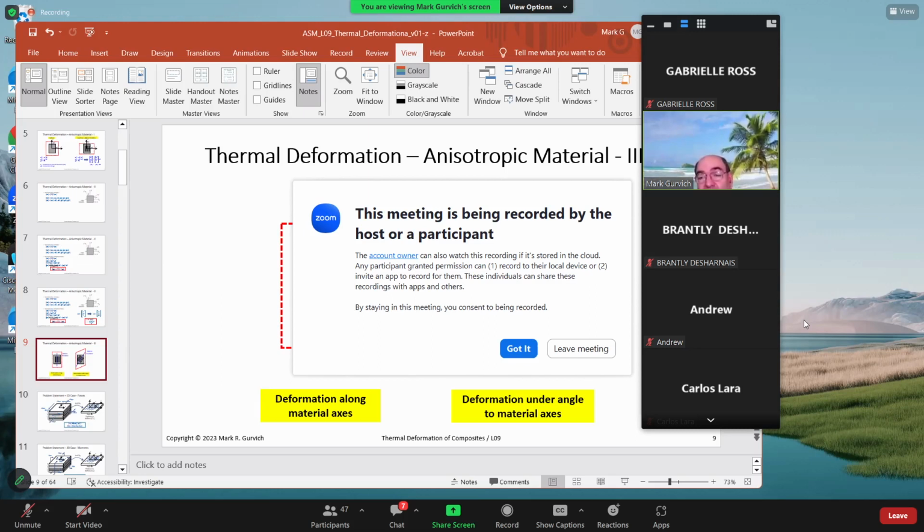It also depends on stacking through thickness, which we will discuss in a follow-up lecture. But bottom line, the thermal expansion of anisotropic material in general is quite different from thermal expansion of isotropic material, not only quantitatively, but also qualitatively, because now we have a completely different phenomenon, mutual shear.